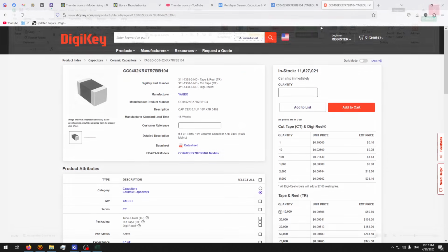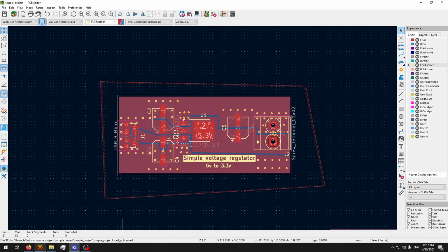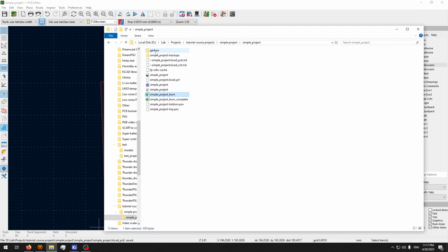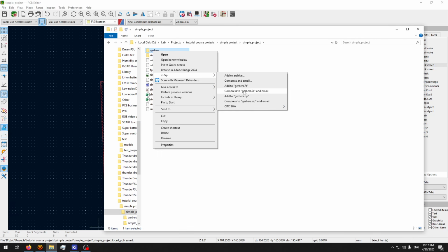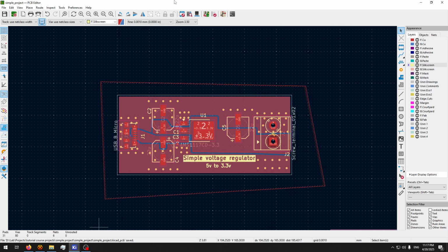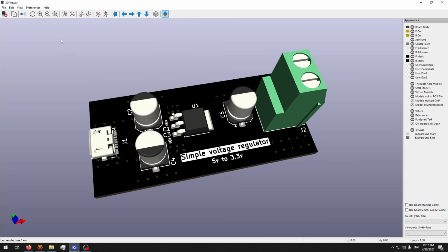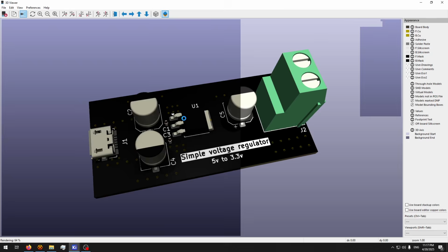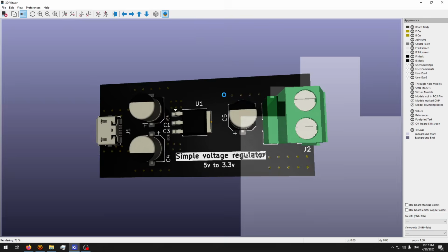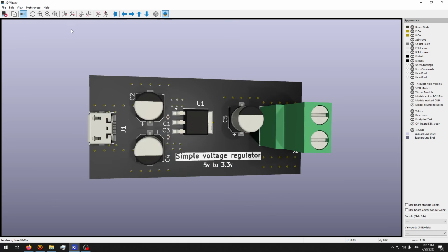Now you have completed the bill of materials, you have completed the layout. Your Gerber files are in here. These are the Gerber files. You can basically zip them together as a .zip folder, and you can send it to your manufacturer and get your board made. Alt 3, I'm sorry, to have the 3D view. Maybe go and do this for a nice little 3D rendered view in ray tracing.